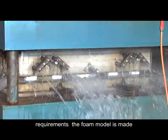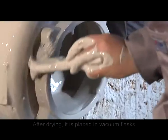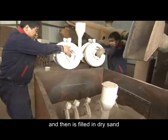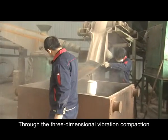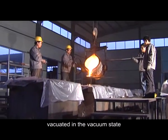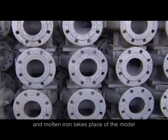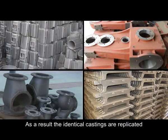First, the foam model is made and coated with special heat-resistant coatings. After drying, it is placed in vacuum flasks and then filled with dry sand according to process requirements. Through the use of three-dimensional vibration compaction, the molten metal is cast in the vacuum state. Meanwhile, the model disappears by gasification and molten iron takes the place of the model. As a result, identical castings are replicated.